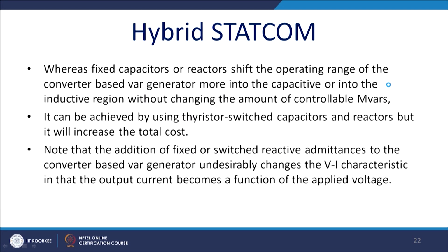Now, what is the advantage of the hybrid Statcom? Fixed capacitor and the fixed reactor shift the operating point to a level. The converter-based VAR generation goes more into the capacitive or the inductive region without changing the amount of the controlled MVAR, but it just actually shifts the y axis, and it can be achieved by the thyristor switched capacitor or the reactor, but it will increase the total cost of the system. It is but an obvious statement.